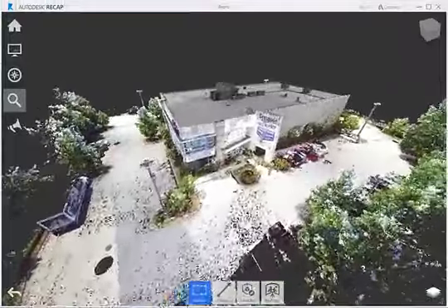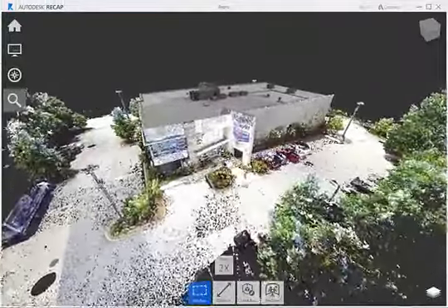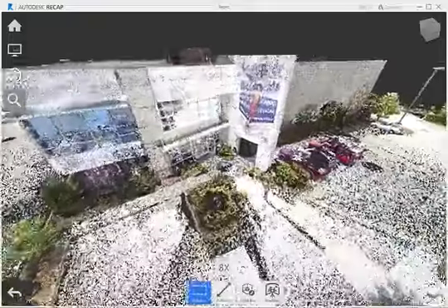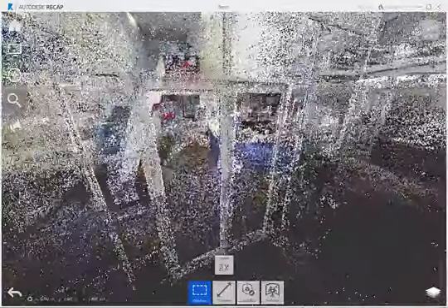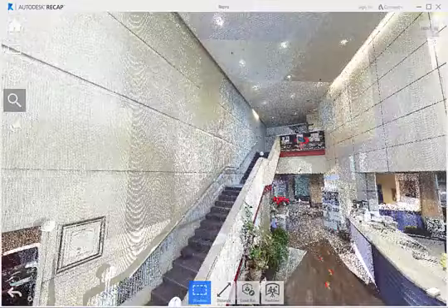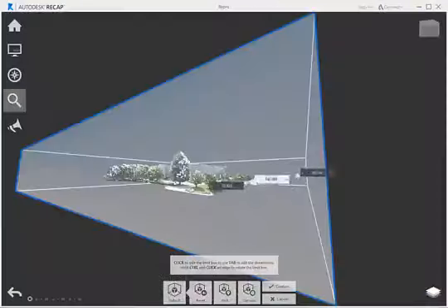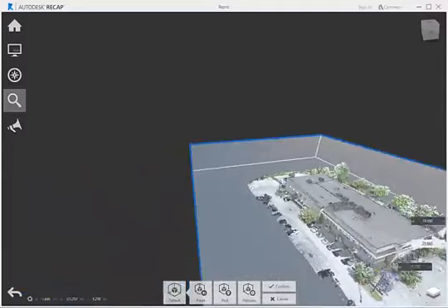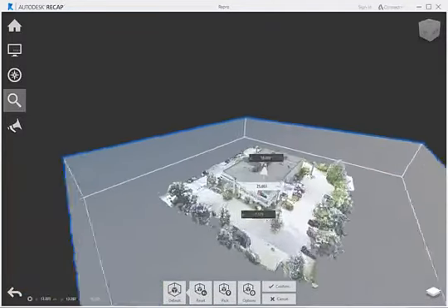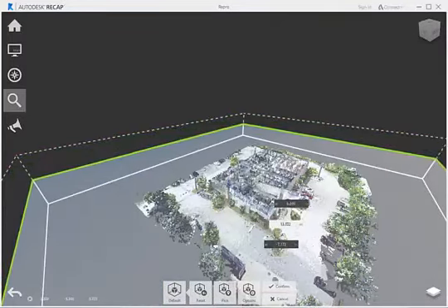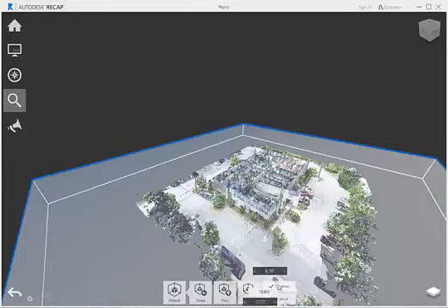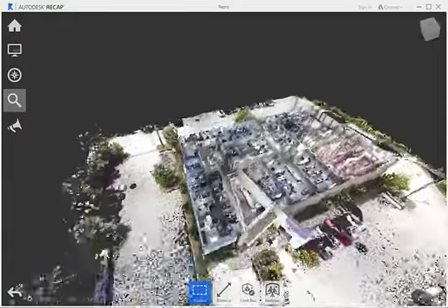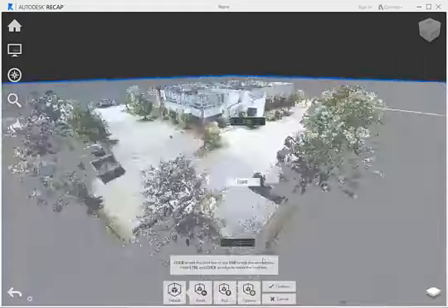When using any of the Autodesk products, we will bring the point cloud into Autodesk Recap. Recap is a high-performance point cloud visualization engine that is not only a standalone application, but is also built into many of the Autodesk design suites. We can use the Recap application to view and navigate the point cloud. By cutting sections of the data, we can view the model in ways that would otherwise be difficult using data collected with traditional means of as-built surveying and measuring.